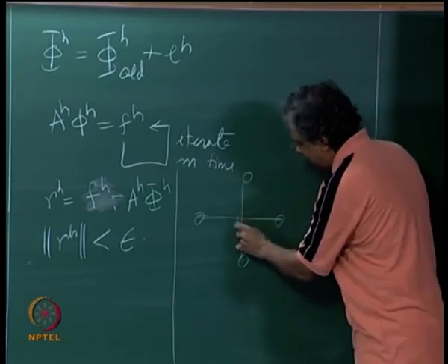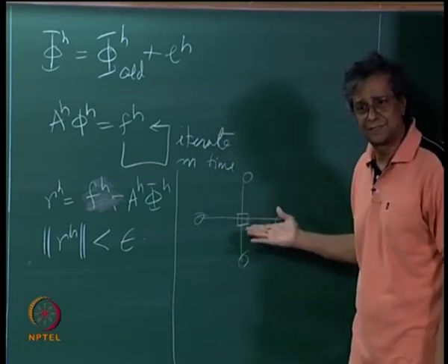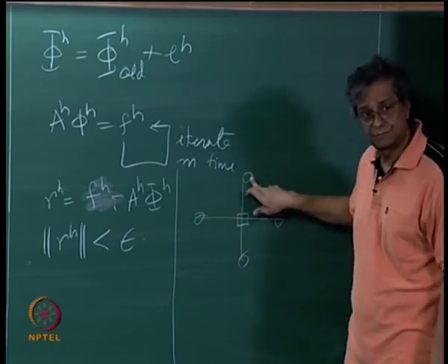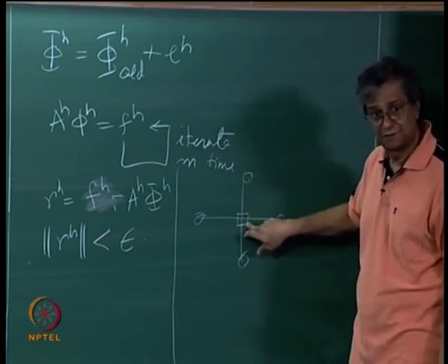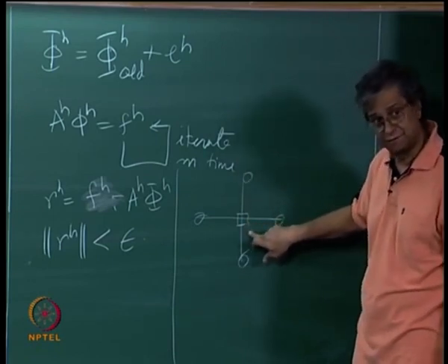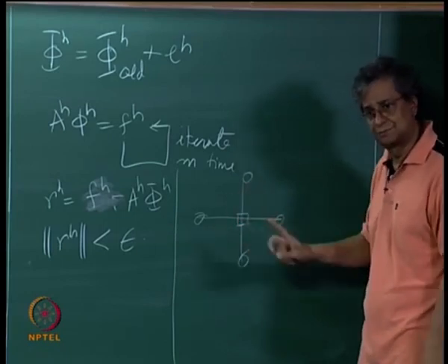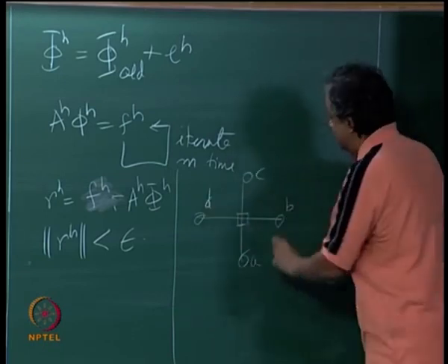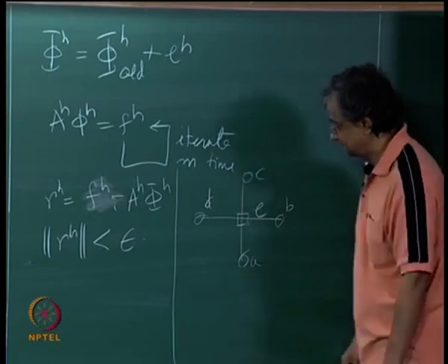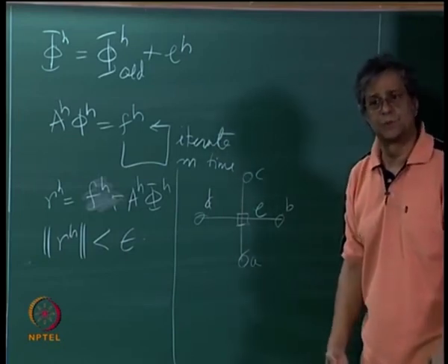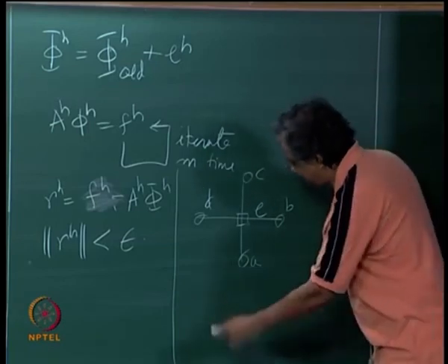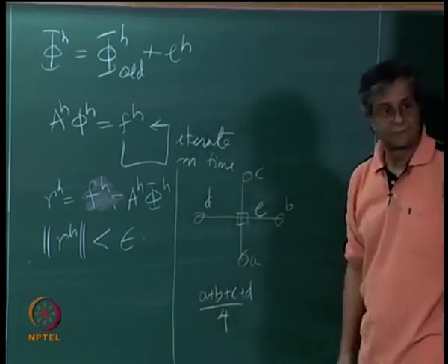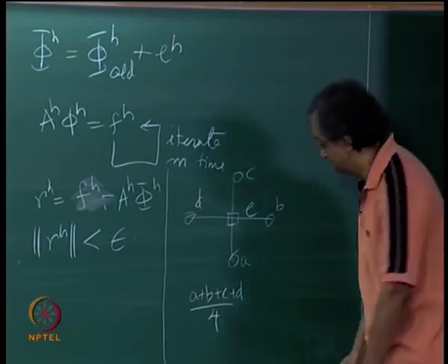I actually have a value here, so I don't want to just throw away what I have at that point. So instead what I will do is I will take the average of these 2, average of these 4, that gives me a central value. I already have a central value, I will take the average of those 2. What do I mean by that? I have values A, B, C, D, and at the center I have E. This is what we would call Laplacian smoothing. What I would do is I would say A plus, that is the Laplace operator, we recognize that for an even grid.